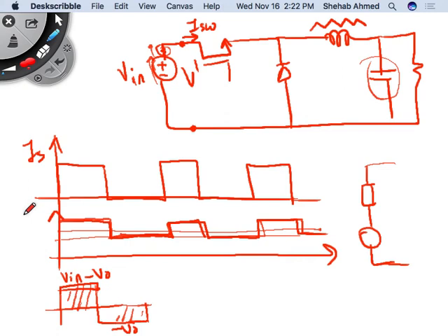This is what? This is a voltage ripple. Exactly. Since this is voltage ripple, like I had here, I had voltage ripple. How do I treat voltage ripple? I add a capacitor. If I add a capacitor at the input, then what happens? Then this still remains as switch current. Will this change? Switch current will never change.